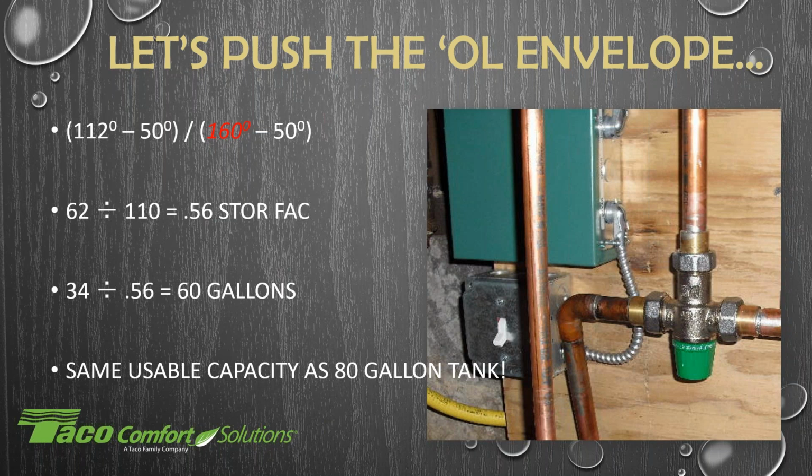If you put a small tankless in your house and you don't have enough, like if you can't run two showers at the same time, adding a mixing valve will not let you do that, because you just don't have the capacity on the heat exchanger itself. So you'd have to add storage, or you'd have to put in a bigger tankless water heater. I hope that answers your question.